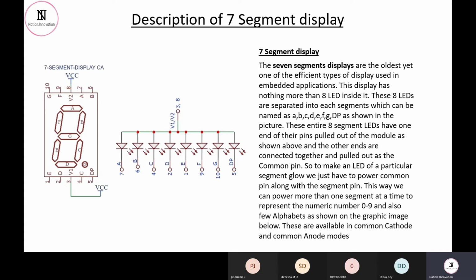The main problem with the 7 segment display is that it uses a lot of pins from the IoT device. Most of the time it is useful for people who just want to display some number, which can be easily done by a 7 segment display decoder or encoder. But in some cases we require direct access to each pin, and then there is an issue because at least 7 different pins are needed to display the segments. If you use a decoder, the number of pins will be reduced, that's for sure.